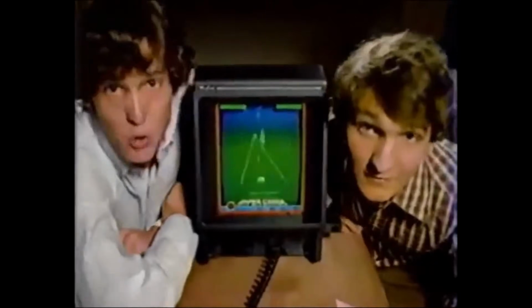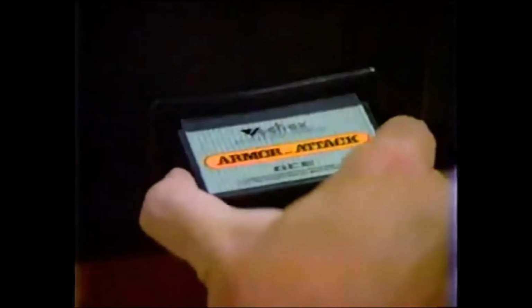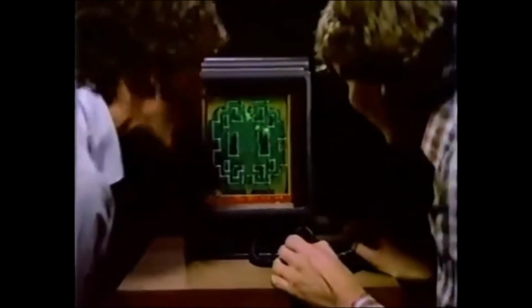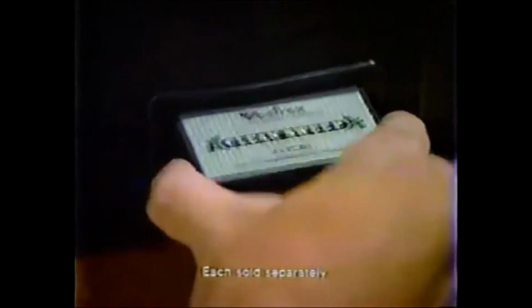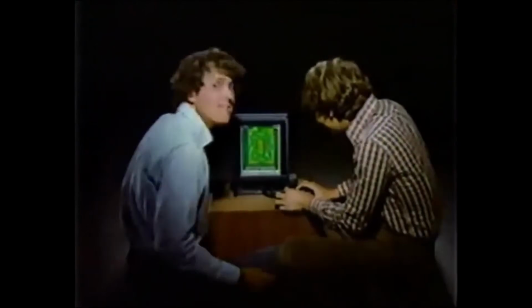I have always been a huge fan of the Vectrex. Unlike almost every other console of its time, it does not connect to a normal television. It has its own built-in vector CRT. Instead of constructing an image from rows of pixels, the Vectrex moves an electron beam directly between coordinates, drawing every line individually. That is what gives games like Mindstorm their incredibly sharp, glowing, and almost holographic appearance. There is really nothing else quite like it.